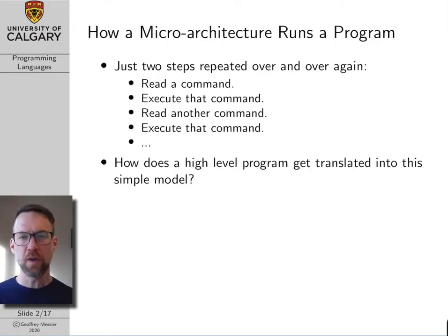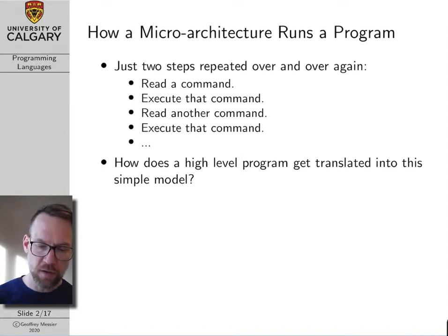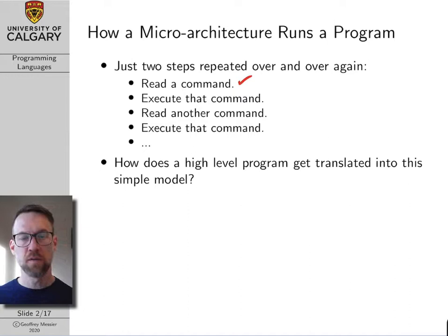To start out with, I want to talk a little bit about how a microarchitecture runs a program. A microarchitecture runs a series of very low-level instructions or commands called machine language commands. If you look at the logic design of how a microarchitecture works, it reads one of these low-level machine language instructions out of memory, feeds it into the processor, and executes it.